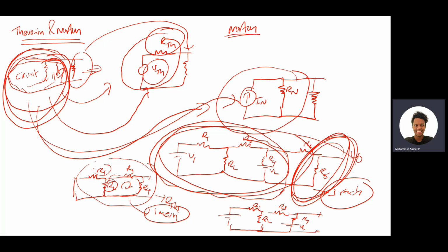Okay. So as I said, this area will be open circuited. Now we can see this is a two mesh problem, right? So this was a three mesh problem, this will be one mesh, and this is two mesh. What basically happens is, if we have an n mesh circuit, and you apply Thevenin or Norton or anything, it will become an n minus one complexity.